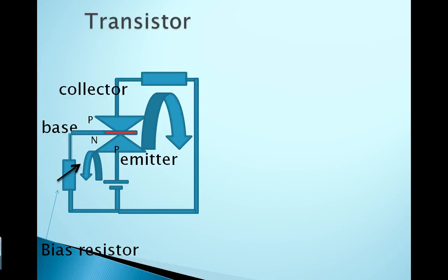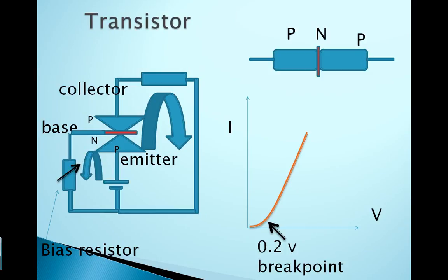Now, the material used for P and N can be obtained by taking a germanium or silicon crystal, where the outer shell is made up of 4 electrons for stability, and by impregnating it with some impurity. The impurity may have less than 4 electrons, say 3 in this particular case for the P, and a hole will be created because we need 4 to complete the crystal. And this hole now can move from one atom to the other, giving us conventional current flow.